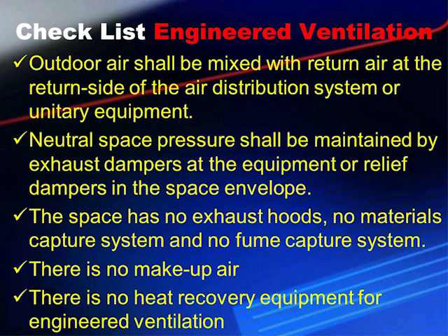Engineered ventilation. Outdoor air shall be mixed with return air at the return side of the air distribution system or unitary equipment. The neutral system pressure shall be maintained by exhaust dampers at the equipment or relief dampers in the space envelope. The space has no exhaust hoods, no materials capture systems, and no fume capture systems. There is no makeup air.